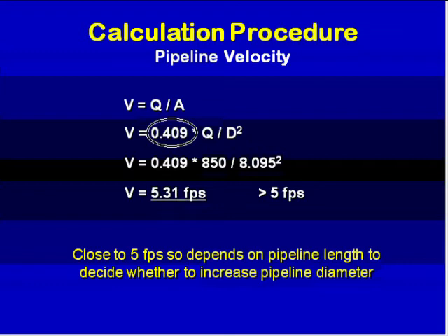feet per second. Now that is slightly greater than the 5 feet per second criteria that would normally be used in a pipeline scenario, but we have many, many systems operating today where the flow velocity is greater than 5 feet per second. The thing we want to have involved in the design of those systems that are greater than 5 feet per second would be some means of distributing the energy that comes with the water hitting the end of the pipeline.